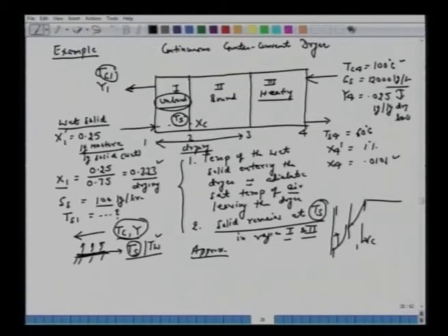Alright, nonetheless, after it has reached this first unbound region, the moisture content is now Xc, and the problem says Xc is given to us, its value is 0.087. Right. So again, notice here, if you recall, we said that this critical moisture content or equilibrium moisture content has to come from this characteristic curve. In other words, one has to do this experiment.